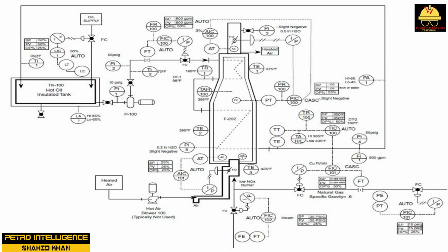Furnace pressure control monitors furnace pressure in the bottom, middle, and top of the furnace with a pressure control loop connected to the stack damper. The middle pressure reading on the furnace is compared to a set point and adjustments are made at the damper if necessary. Furnace temperature control adjusts fuel flow to the burners, and, as flow exits the process furnace, monitors process conditions. The natural gas flow controller, slave, is cascaded to the master temperature controller. The temperature controller adjusts fuel flow to the burners.